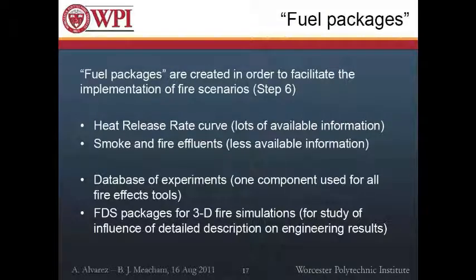Also, we looked at design fuel packages, in order to facilitate the implementation of fire design scenarios. Basically, we look at information such as the heat release rate curves and smoke and fire effluents. So we started to create a database of experiments which could be used for any fire effect tools. And we also looked at creating FDS packages for 3D simulations.